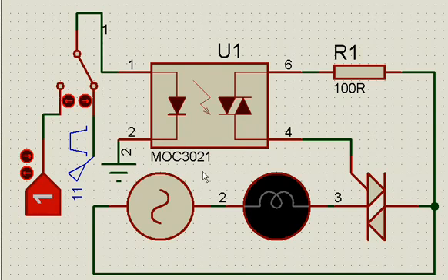But if you switch over from this particular IC to another IC called MOC 3060 or 3063, they are zero voltage type, and you will always get zero voltage switching. That is the biggest advantage of using an opto isolator. The triggering takes place from the same source.